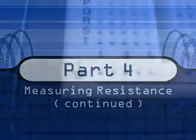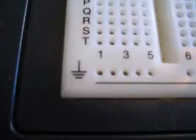An important concept in electricity, closely related to electrical continuity, is that of points being electrically common to each other. Electrically common points are points of contact on a device or any circuit that have negligible, extremely small resistance between them. The ground or negative connection on a protoboard or breadboard along the bottom in this picture are electrically common to each other, because there is electrical continuity between them.